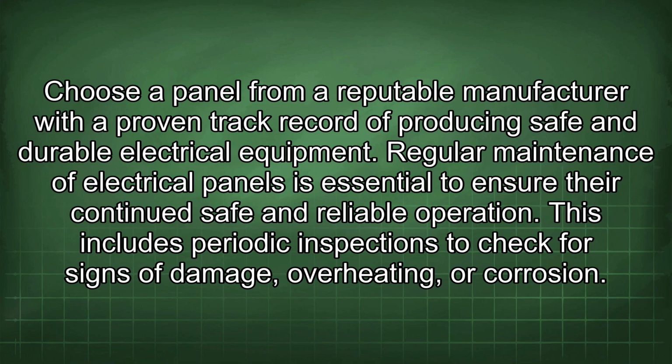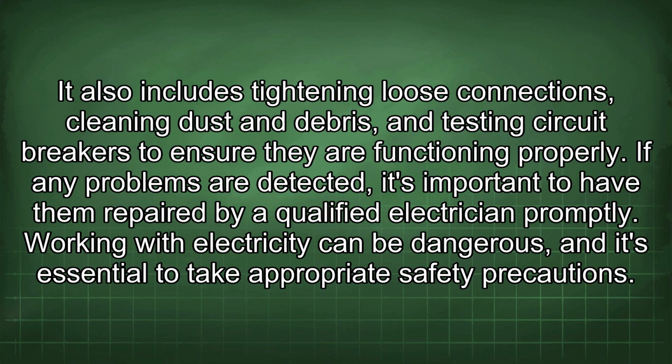Regular maintenance of electrical panels is essential to ensure their continued safe and reliable operation. This includes periodic inspections to check for signs of damage, overheating, or corrosion. It also includes tightening loose connections, cleaning dust and debris, and testing circuit breakers to ensure they are functioning properly. If any problems are detected, it's important to have them repaired by a qualified electrician promptly.